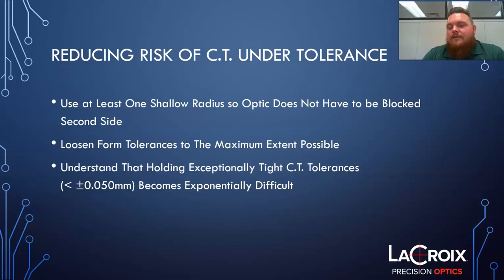I understand the software gives you a specific form tolerance that you need to hit, but when I ask for this, I mainly am asking with regard to the safety factor. On materials that are tamer than the fluorides or high expansion materials that we have been discussing, most definitely a larger safety factor on the end of the designer is still potentially reasonable for manufacturing. But please try to keep that safety factor as small as allowable for these types of materials. Just please try to give us as much form tolerance as available in the system.